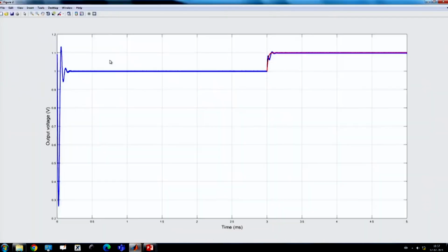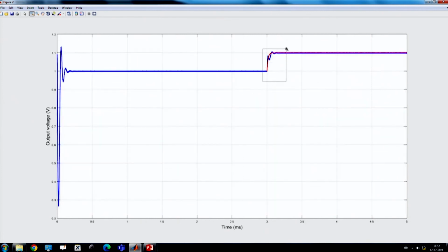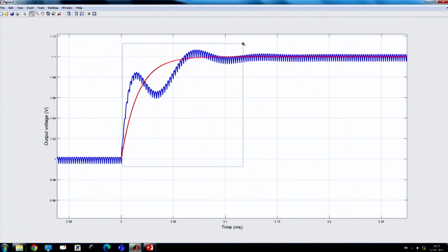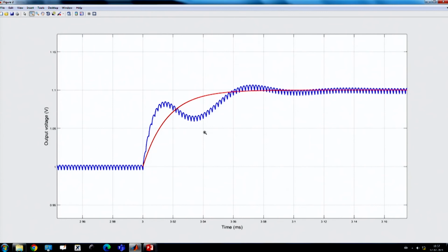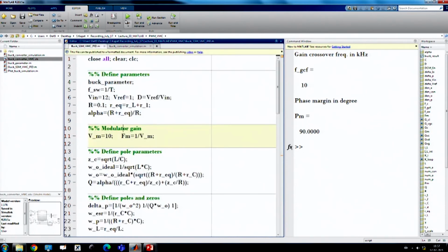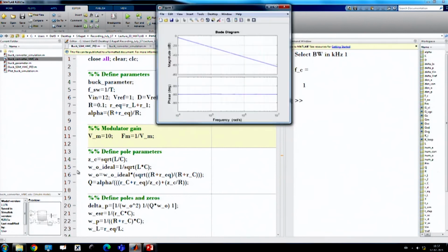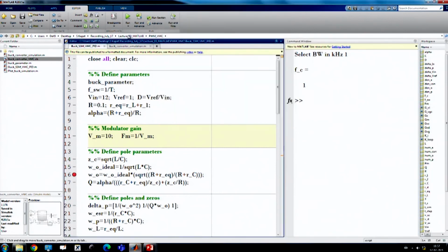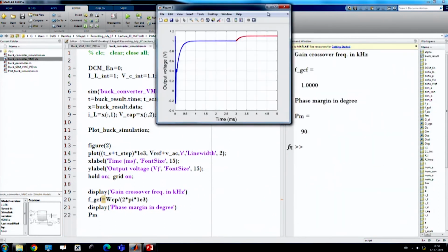You see when you reduce to 10 kilohertz, the response again becomes slightly different. Initially it was matching the initial response, now the problem starts even in between. So, the response is clearly showing it is not perfectly matching. Now you further reduce, to let us say 1 kilohertz, which is too low, to match the switch simulation. So, it is 1 kilohertz, 1 by 500 times slower.